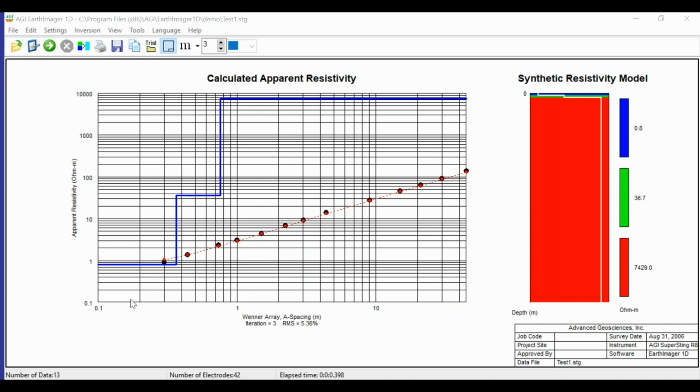Okay, Ali is correcting his question. I meant the length of the electrode into the ground for sounding. Yes. Generally we have stainless steel electrodes of about 45 to 60 centimeters. Depending on your electrode spacing, you can put them down like 30, 40 centimeters.